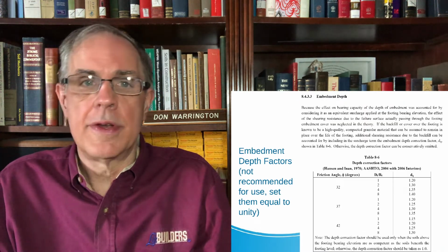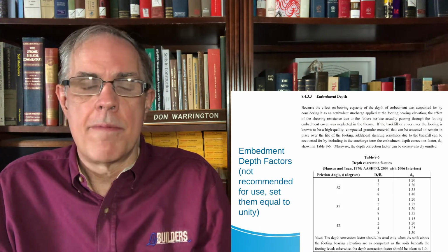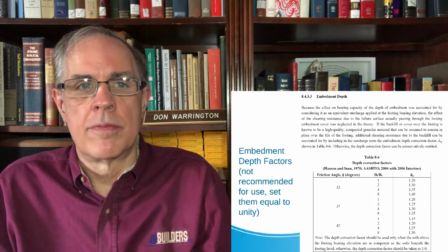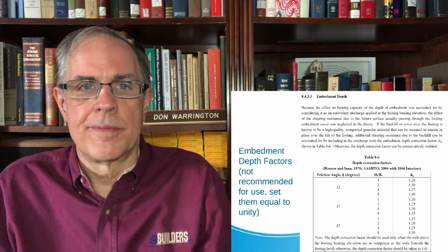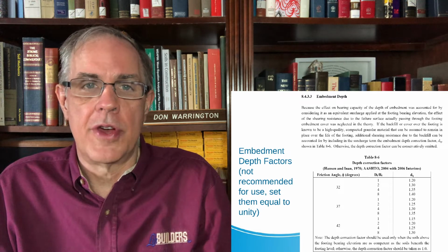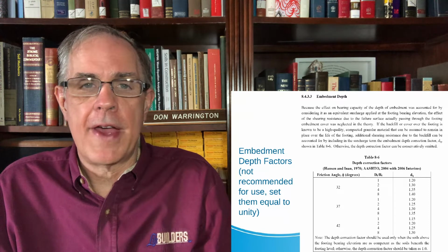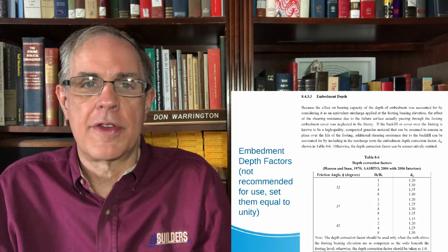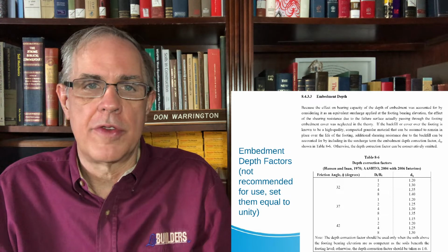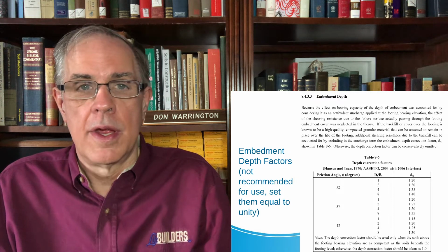The last one is embedment depth factors. The short answer is don't. Embedment depth factors assume that the failure surface extends all the way to the surface of the soil instead of just the base of the foundation.